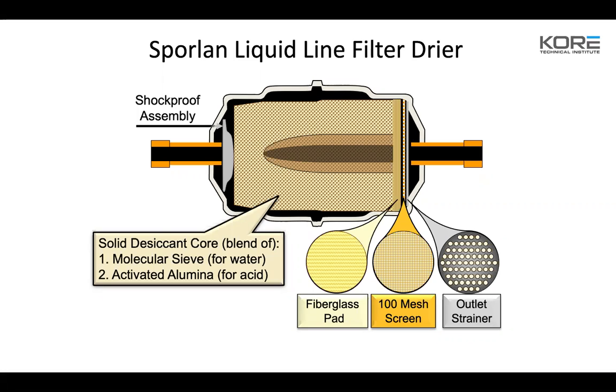about clamping temperatures is sometimes you get the ambient air mix around that. So you've got to make sure you're getting a good pipe test. But the best way to do it is if you have a pressure tap on each side of that, and you get a 2 PSI pressure drop across it. So you better make sure your gauges are calibrated. You're going to want to see that. That's what Sporlan recommends.